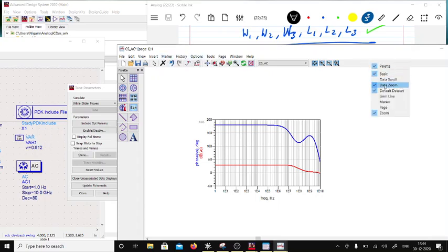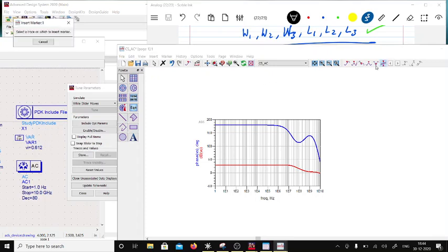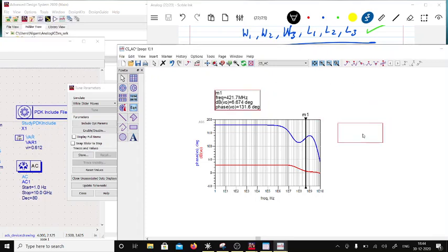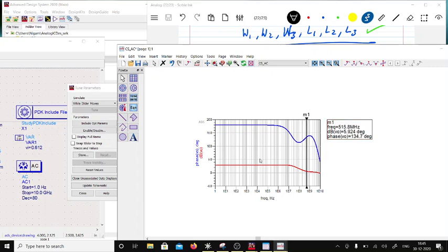Marker, see what it does. The gain it is showing in degrees, which is wrong, which is dB, right? I've been asking Agilent for a long time to please correct this, and they don't want to correct this. So I am on a YouTube platform forcing them to correct this. Okay, so you see here there is the gain of 0, and I now have a 65-degree margin.